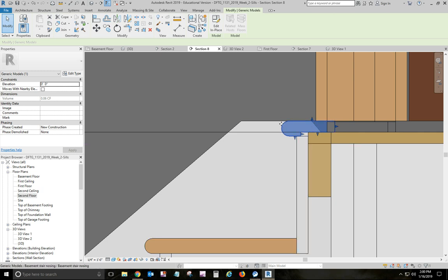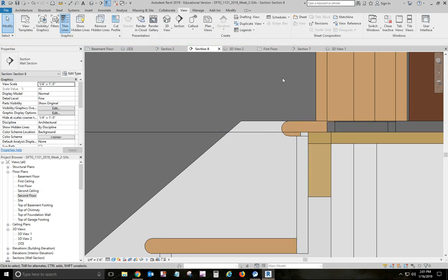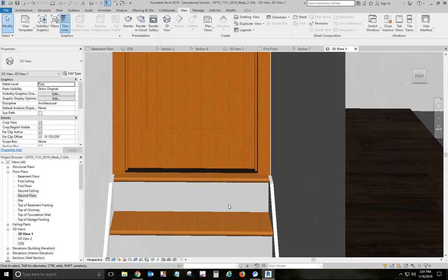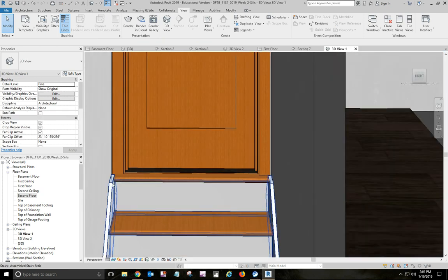So you can start an extrusion, model a component in place. You can choose the stringer as your plane that you're going to sketch on. You can sketch this thing out and get it in the right location, and then extrude it across from stringer to stringer. Okay.